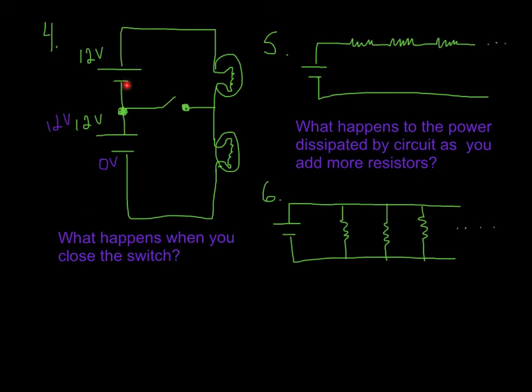All right, these are connected here, so this is 12 volts down here. Let's just write that so we realize that. This is also 12 volts then at this low side of the battery, and that means that this is 24 volts up here. Cool. All right, do you get that? It's getting a little crowded here. So if this is 0, that's 12, that's 12, that's 24. And so what we see here is 24 volts with the switch open.